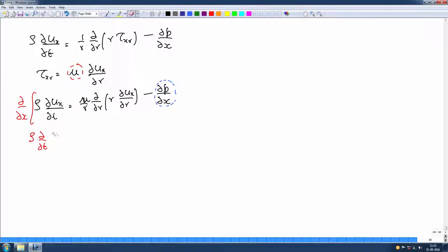So, in the next lecture, we have obtained the equation here. Now, we have to solve for the velocity profile and then see if we can get results for the friction factor as a function of Reynolds number and so on. That part, the velocity profile and the friction factor, we will continue in the next lecture using this particular equation for the momentum balance. We will continue with pipe flow in the next lecture. First, we will derive the equation for a steady flow, and then we will look at some examples of unsteady flows.